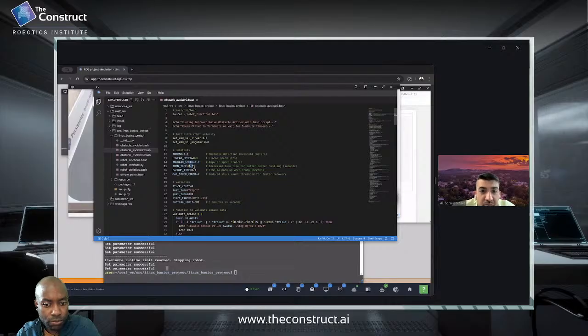I calculated 0.3 by trying different things to see which combination of these two gives us 45 degrees, because this is 0.15 radian. So we have 45 degrees. 45 degrees was your prime value, the angular distance that you thought would give you proper obstacle clearance. Yes. Because if it was less than that, it's rotating not a lot, so we would have to turn multiple times. But with this, if there are obstacles, it can just turn. Okay, I see.